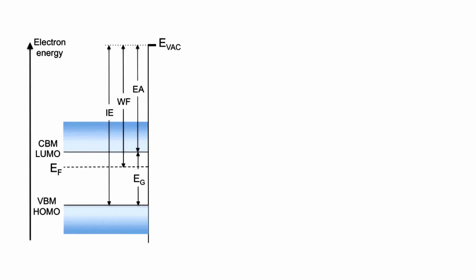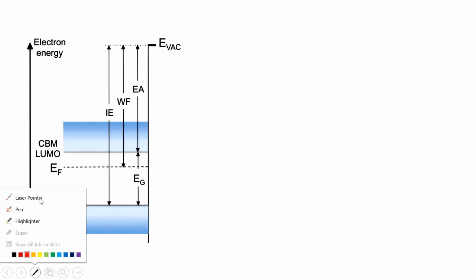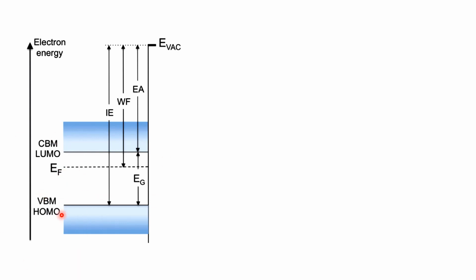So I'll just explain this question. Whenever we are talking about energy band diagrams, we'll be having something like this. This is known as the valence band. At normal temperature, that is at equilibrium temperature, it will be completely filled and the conduction band will be completely empty. Whenever we provide sufficient energy, electrons from the valence band will be excited to the conduction band, leaving behind holes.